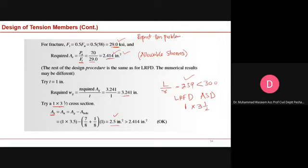If I ask you to use an angle, any angle, or I can say an equal leg angle, then you don't even have Ag, what will you do? Then you will have to go to the manual. How will you go to the manual? If I ask you to use a wide flange section, you can do it on any wide flange section, you can also do it on an angle. But the issue is how you will find its Ag.